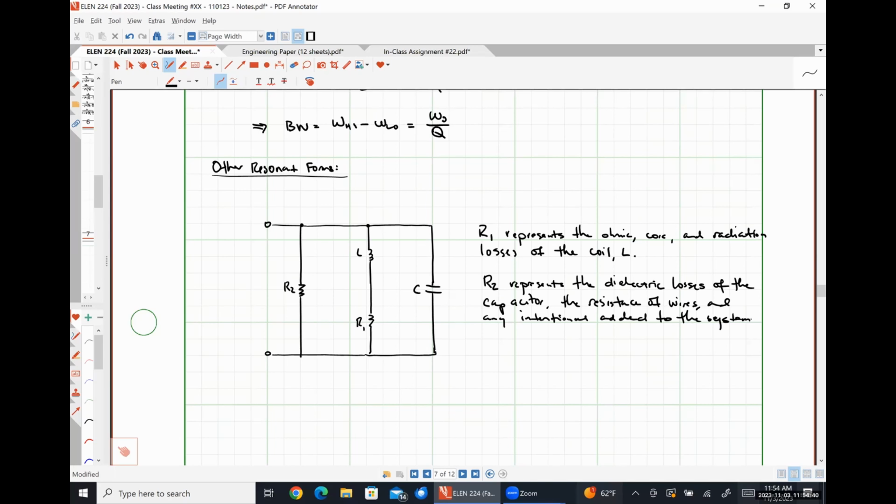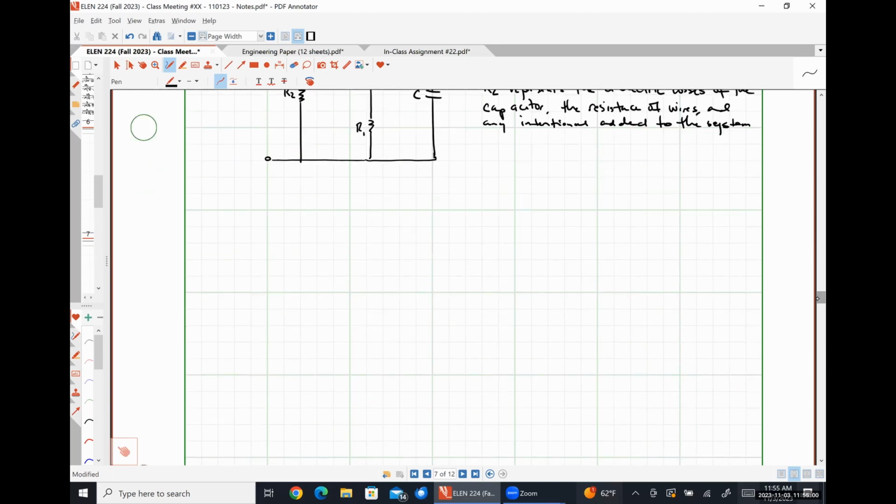This is as simple a model as we could possibly get that is valid over all frequencies. So what we're going to have to do to simplify this is develop relationships that are only valid over our frequency band of interest. And then we will wind up having a representation that looks something like this, which would simply be some equivalent resistance. I'm going to call this R sub E. I'm not using R sub EQ because I don't want it to come off like we're just doing resistor combination, because we certainly are not.